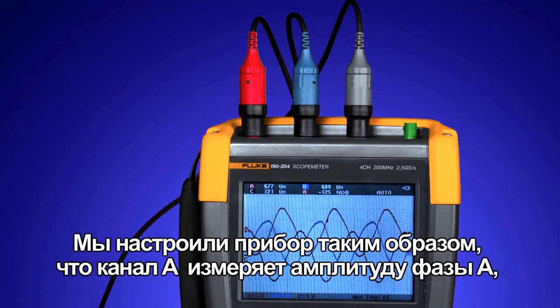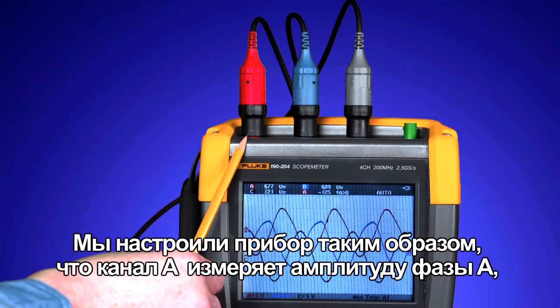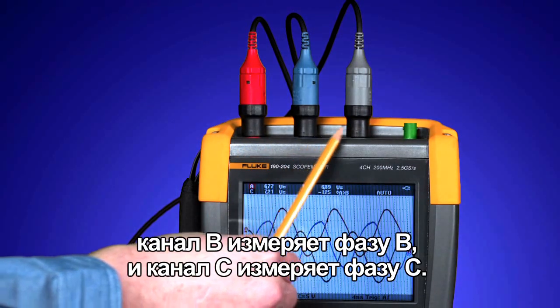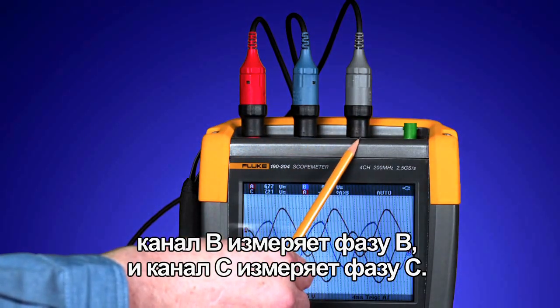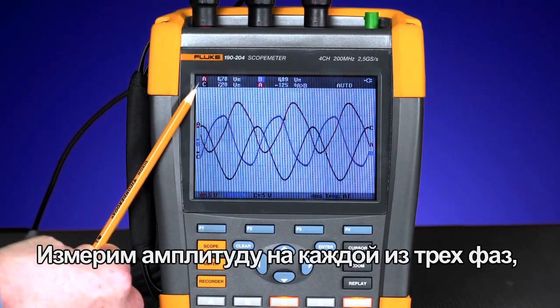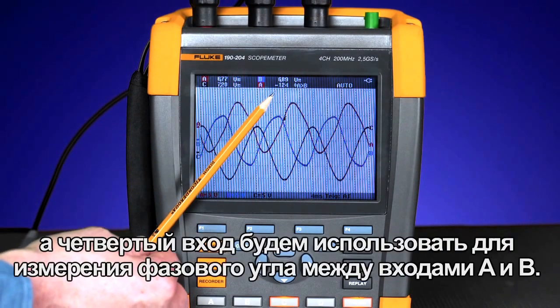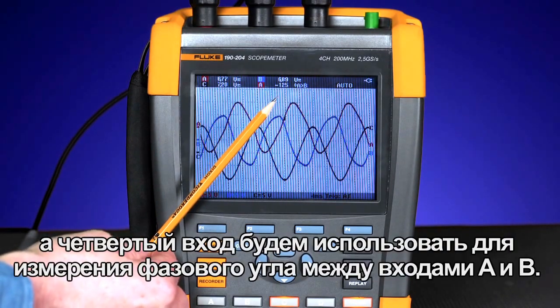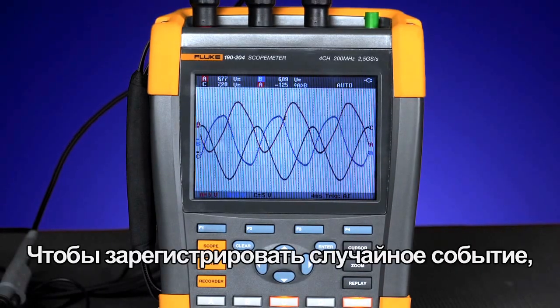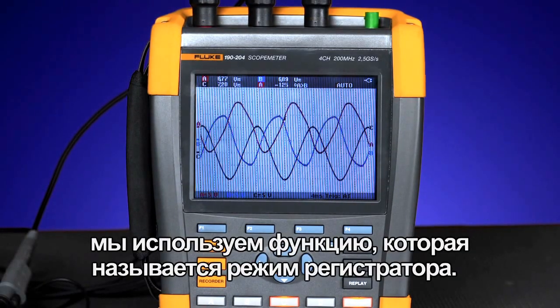We have our inputs set up with channel A measuring the amplitude of phase A, channel B measuring phase B, and channel C measuring phase C. Our defined measurements are the amplitude on each of the three phases, and the fourth input reading the phase angle between input A and B. In order to capture a random event, we'll use the function called recorder mode.